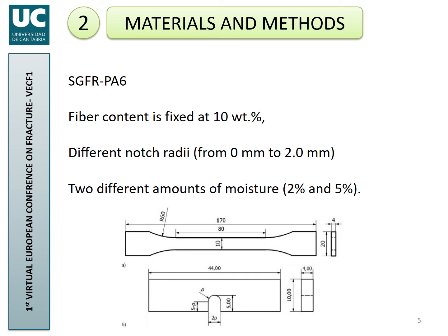Some of them, just a few, were used for tensile testing, and the rest of them were cut in the middle part to obtain the fracture specimens as that shown in the lower part of the figure. The defects were performed by machining the material, except for the crack-like defect, which was obtained by sawing.